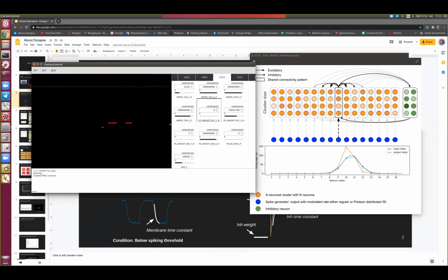These are just 16 single neurons on this particular core, indexed from 1 to 16. And with Python, I configure the onboard FPGA generator to send Poisson spike trains with rates that correspond to this blue curve. So it's the input rates. And here, every neuron, when it spikes, lights up. We can also record these events.